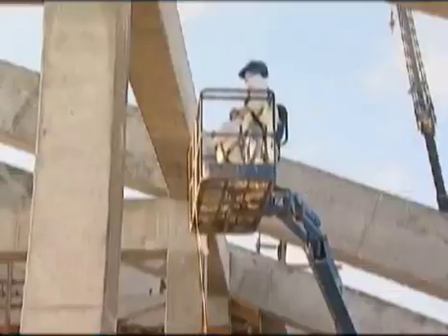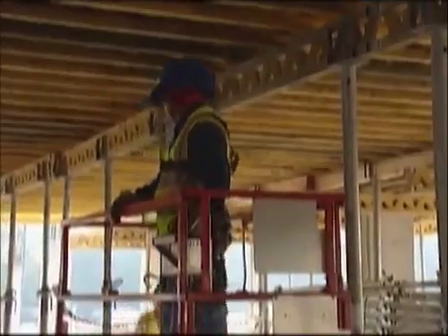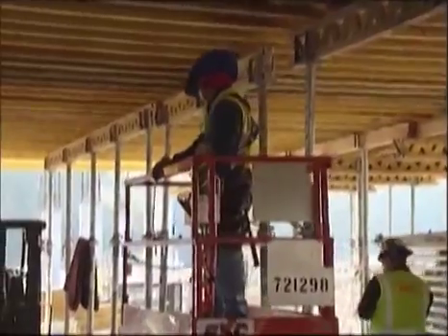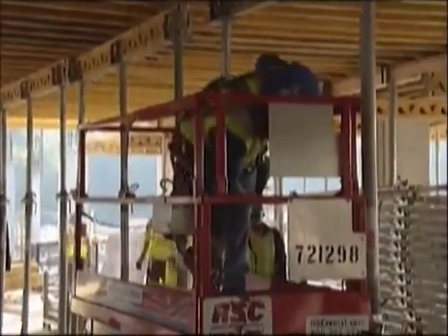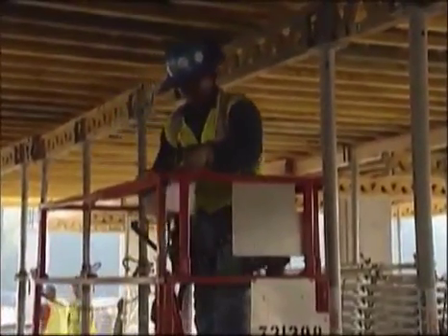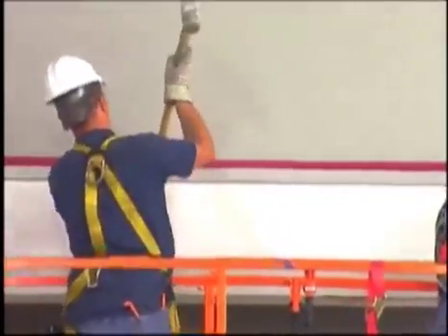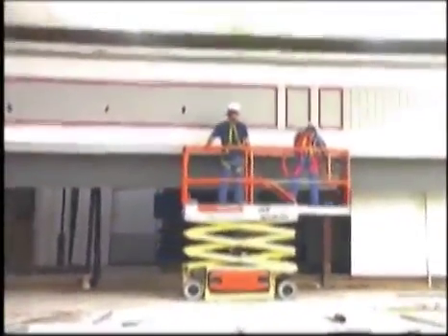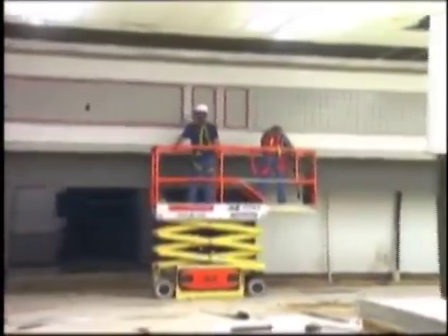Fall protection is required for all personnel that perform work on a lift, even if the lift is used according to manufacturer's guidelines and all safety precautions are followed, because the chance of a fall is minimized, not eliminated. All scissor lifts require fall protection. Guardrails that are properly designed, maintained, and meet OSHA guardrail requirements are sufficient fall protection. If the guardrail does not meet OSHA standards, or if an employee leaves the safety of the work platform, then a personal fall arrest system utilizing a full body harness is required.